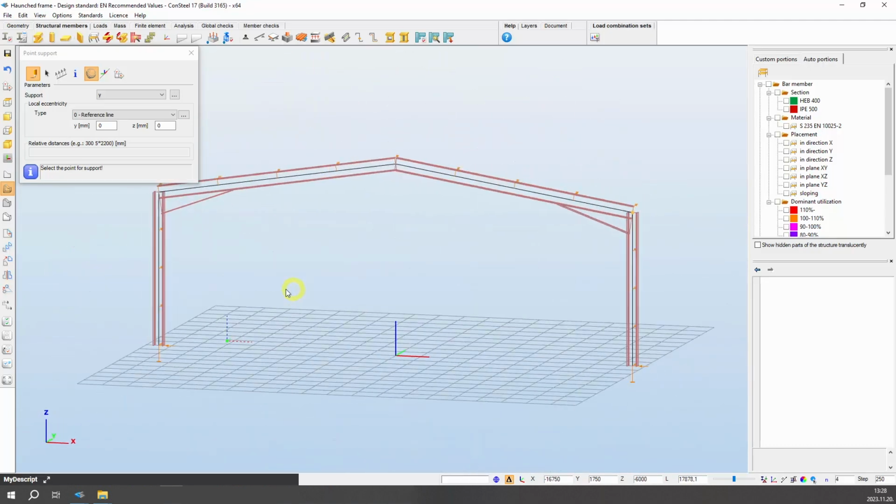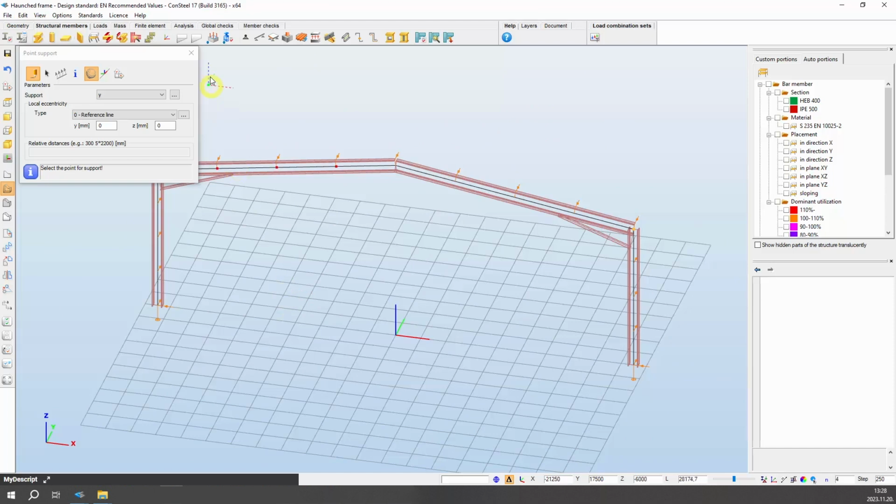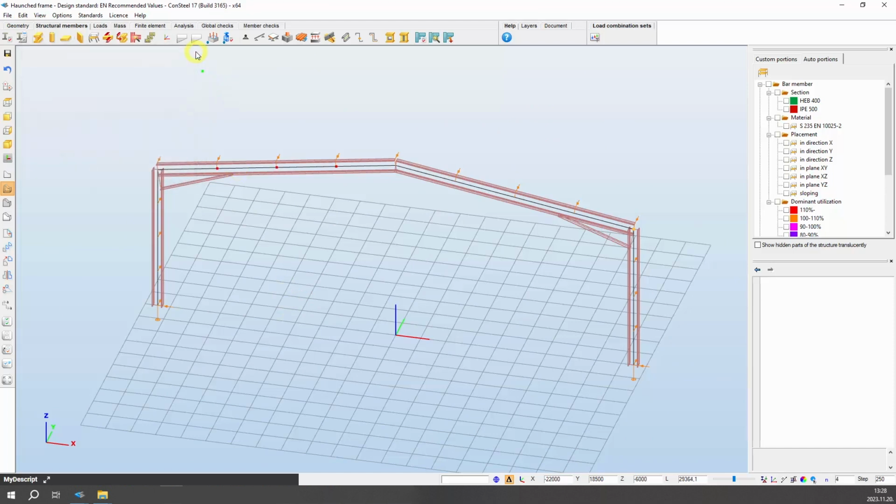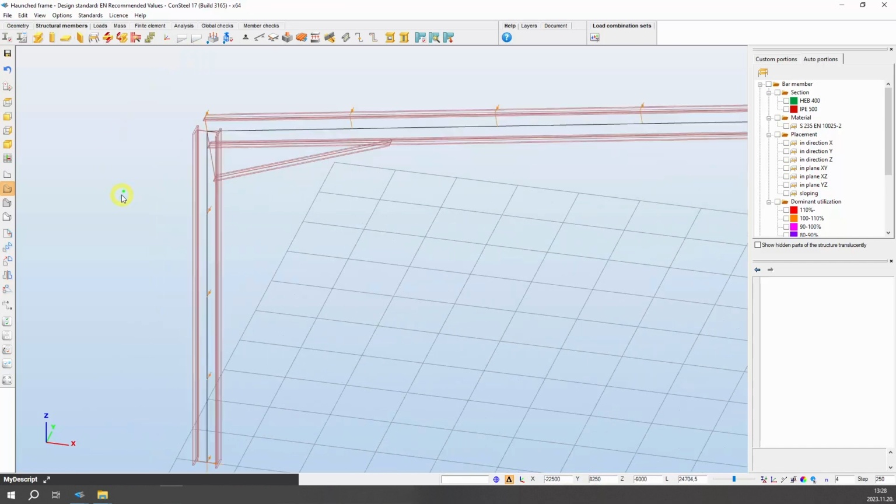We are almost done with modeling the structure. However, for the accurate calculation of the out-of-plane displacements and buckling modes of such frames, the special mechanical behavior of the frame corner zone should be considered. The main mechanical background is that these, generally stiffened, corner zones have usually significantly different behavior than the connected beam member, influenced dominantly by shear effects due to their short length. Connected members, in contrast, demonstrate beam column behavior with a dominant bending effect.